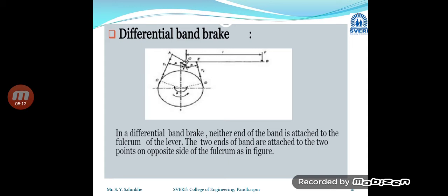It also depends upon the surface roughness. So if the surfaces are rough, the coefficient of friction is higher. If the surface is smooth, then the coefficient of friction will decrease, but it is a little change. In most cases, in the case of frictional force, Rn, that is the normal reaction, plays a very vital role.